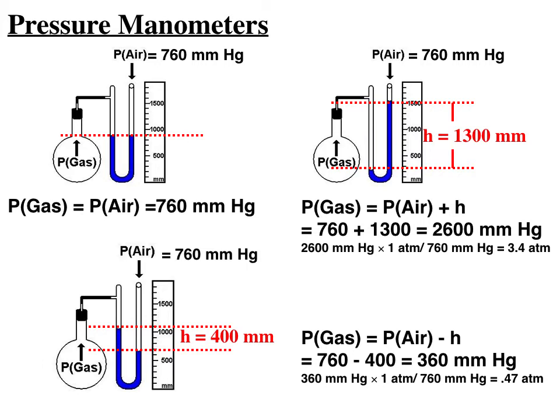And I'll clarify that maybe more in a second, but let's suppose for the instant here that the mercury manometer arms are stationary. They're not moving any further. So once again, on the left side, the gas molecules are rushing up the hose and down the tube and pushing on the left side of the mercury. Air from the outside is running down through the open end of the right manometer arm, pushing down on the surface of that liquid, yet the liquid is in an imbalance.